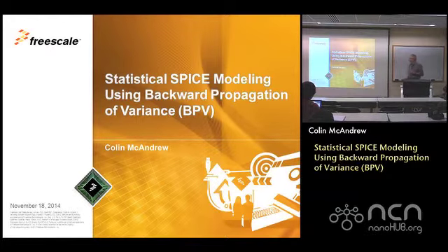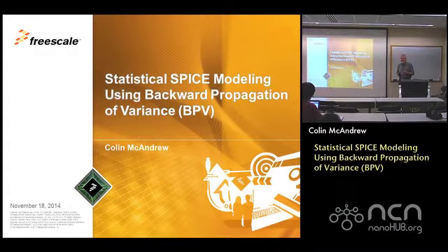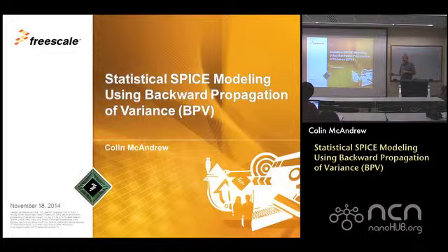So what I'm going to be talking to you about for the next hour is statistical modeling for semiconductor devices for circuit simulation. It may look a little bit esoteric, but this is our standard practice within our company for how we actually determine the statistical models. We have two general purpose programs for doing the statistical modeling that I wrote. One of them characterizes global variation, which is the overall variation of parameters, and the other characterizes differential performance between two devices, which is mismatch.